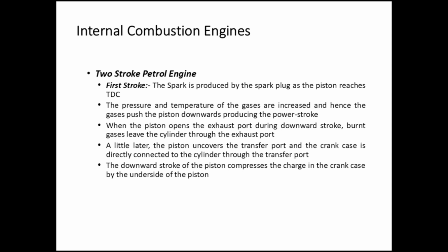When the piston opens the exhaust port during downward stroke, burnt gases leave the cylinder through the exhaust port. A little later, the piston uncovers the transfer port and the crankcase is directly connected to the cylinder through the transfer port. The downward stroke of the piston compresses the charge in the crankcase by the underside of the piston.